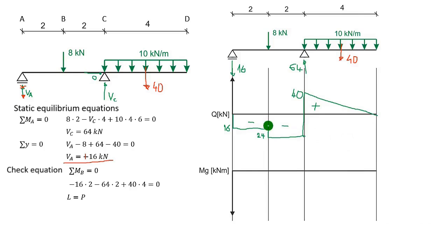Okay, now the moment. The moment is a bit more complicated. We can calculate it in two ways. First, I'll show you a method where we calculate the moment at a specific point. Then I will show you a method where we can draw the moment diagram by calculating the areas of the shear force diagram. Okay, but first the moment at a point.